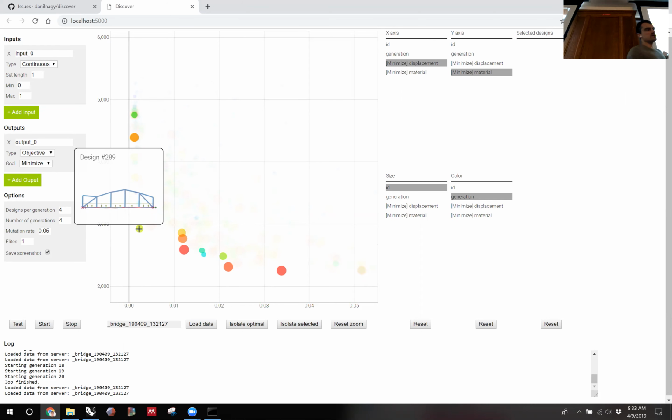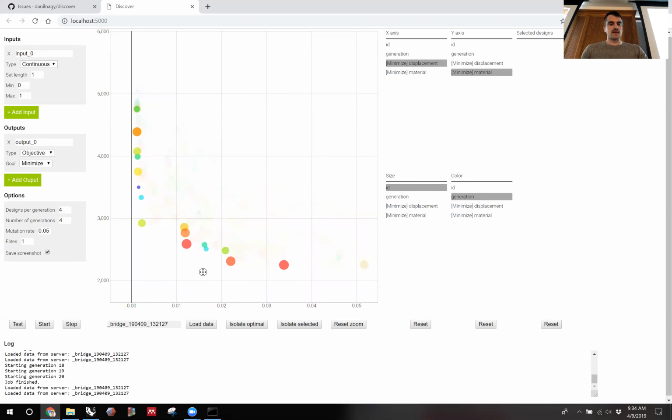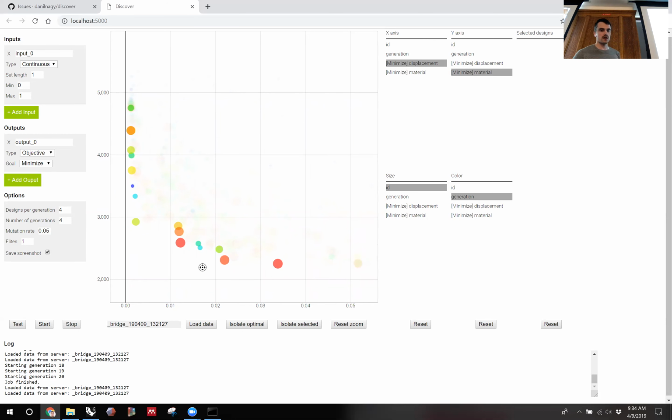And with this kind of linear structural analysis, it's not going to tell you anything about the point where the material actually starts to break apart, but it will tell you how much the stresses are. So typically what we do is we treat the stress as a constraint. We want to optimize for the lightest structure, the stiffest structure, but we also want to make sure that no part of the structure exceeds the structural limitations of that material. So what we're going to do next is actually implement that stress criteria as a constraint in our optimization and see how that starts to change the types of designs that are produced. And hopefully it's going to start to produce more realistic designs.